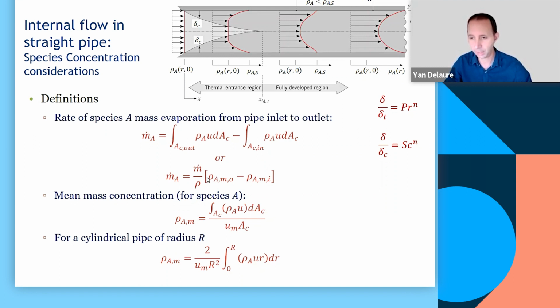The equivalent to this is given as the second equation, where we use the definition of the mean of the concentration and the concentration of the mass. Okay, so M here stands for the mean, written like this: mass concentration of species A at the outlet, and you take the mean. So that means you don't have to use that area integral. The definition of the mean is provided here, and for a cylindrical pipe, the area integral ends up being this, with this coefficient there.